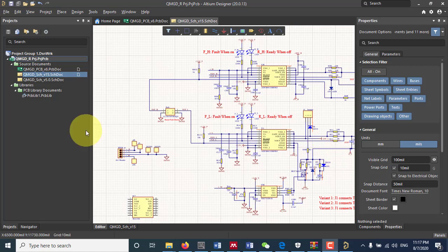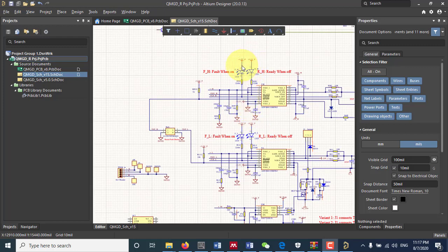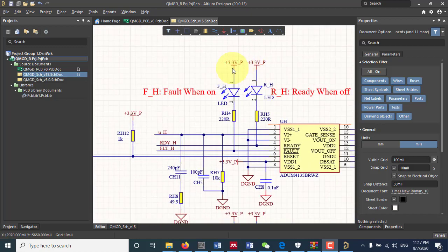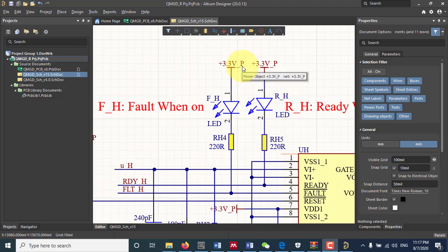Although we'll discuss the buildings in the upcoming videos, how to build up your schematic and how to navigate through your schematic, for the beginning, let's see how the net operation works. For example, if we are using a DC source here, let's say 3.3 volt, we are using this net, and wherever else we use this net, it means that it's connected with that point.